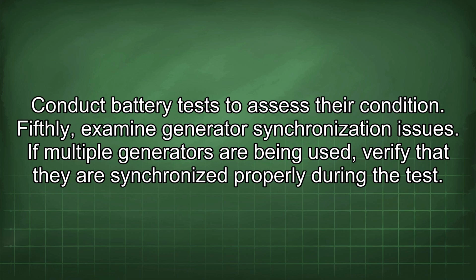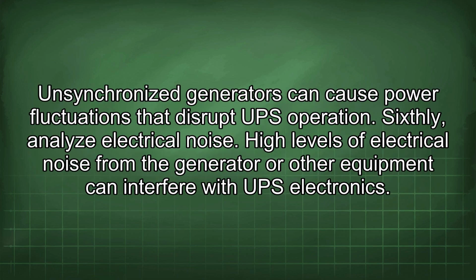Fifthly, examine generator synchronization issues. If multiple generators are being used, verify that they are synchronized properly during the test. Unsynchronized generators can cause power fluctuations that disrupt UPS operation.